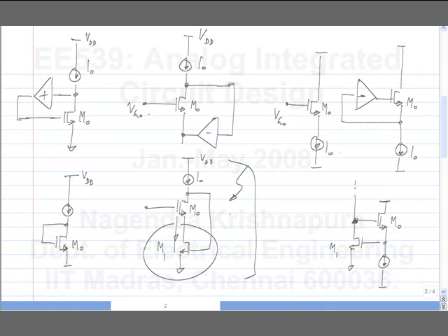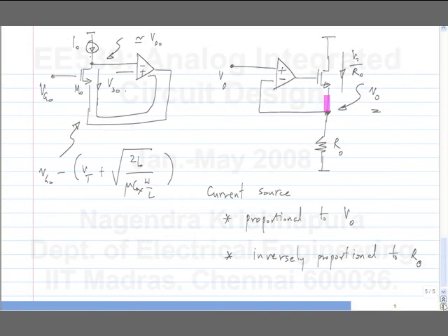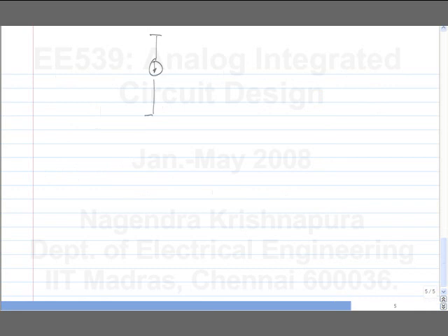Okay. But if I really wanted to, and if I had infinite liberty with my choice of components, I could do this. So, this will ground my source for incremental, small signal increments, right, as long as they are at AC. So, then I can apply Vg0 plus my input voltage and take the output from here. Okay. Of course, this is not practical at all, but if I really wanted to do it, this is how I would do it. Which one? This one? We will see soon.